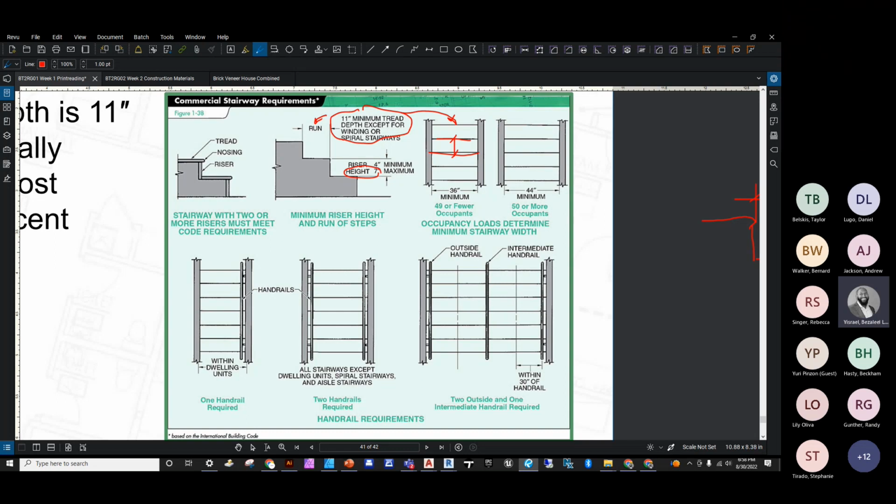Think about it: we want to make it easy for people to navigate and travel between spaces vertically, right? If you have 14 feet and beyond, people are just going to get tired. That's why we put escalators in commercial spaces like malls. Just think about some malls, even international malls, there are stairs, right? Those stairs have a landing. If they didn't have that landing, it would be quite taxing on us, especially these Americans here, right?